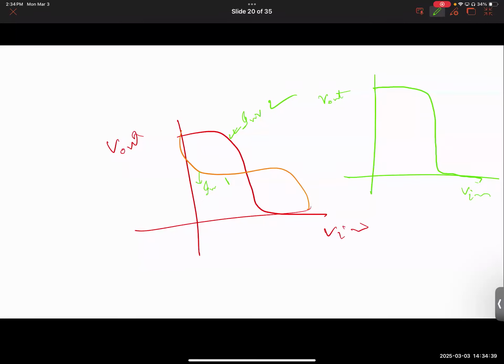For this, if you're dealing with inverter 1, whether you're increasing or decreasing the voltage, it's the same VTC for the same inverter. Okay. But here, for the ferroelectric inverter, the NCFET-based inverter, for one kind of sweep, you follow this path. For the other kind of sweep, you follow a slightly different path.